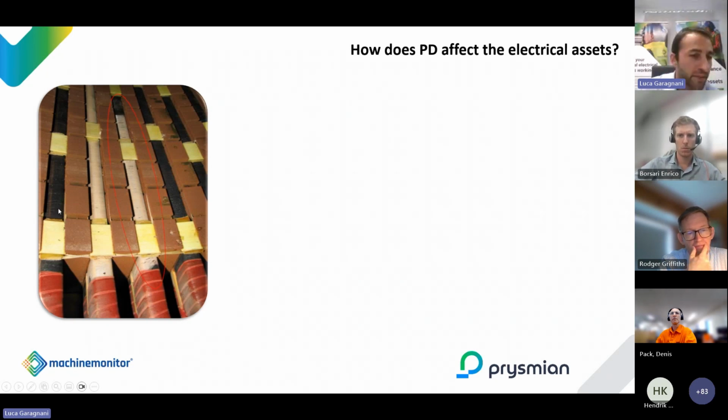If this material is too resistive, it will build up a very high potential across this little gap. And this high potential will be the highest in correspondence with the high voltage coils. You can see very well here, starting from here, we start to have discharges that eroded all the slot coating over time, and all the coating on the high voltage bar is gone. What is this? It is a manufacturing issue. Obviously, the coating selected and the air gap were not compatible and generated this discharge.